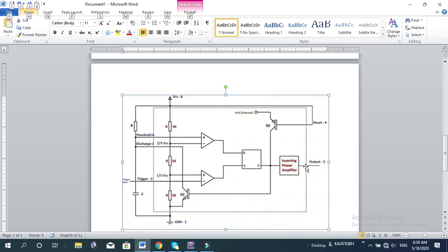Okay. At the same time, the output of the flip-flop turns on the transistor Q1 because it goes low. So it turns the transistor Q1 on, and hence the capacitor C gets rapidly discharged through this path. So C gets rapidly discharged through this transistor Q1. The output of this monostable remains low until the next trigger pulse appears. Okay, so then the cycle repeats.